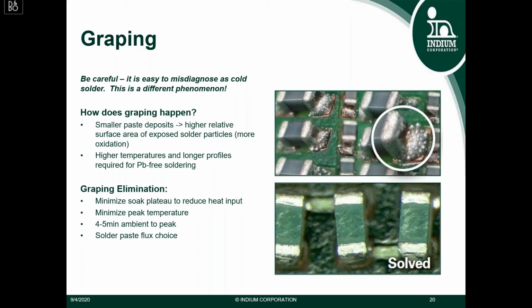And finally, you can also eliminate graping with a solder paste flux choice, such as a more thermally stable flux vehicle or a more aggressive flux vehicle.